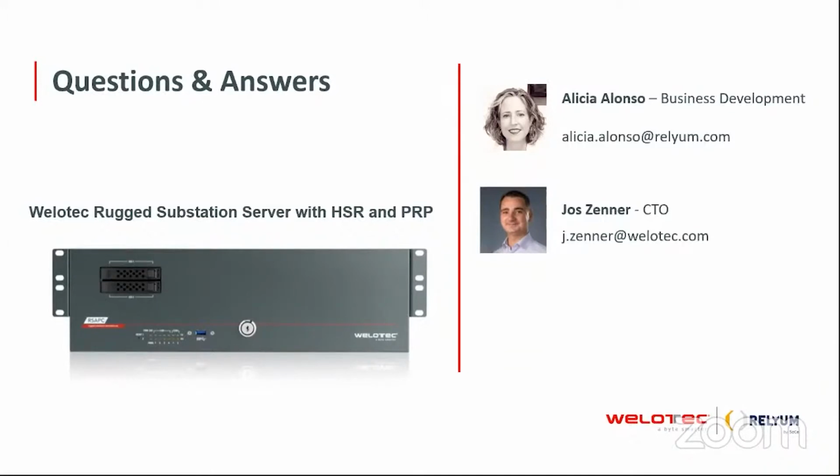Omar has a question, I think it's for Alicia, or a couple of questions actually. One is, HSR is based on layer 2 protocol and PRP is based on layer 3, right? No, in fact, the two are based on layer 2. The two work at Ethernet level, and it is one of the benefits in terms of management and configuration, and also is the fact that it can be implemented in critical and low latency networks.